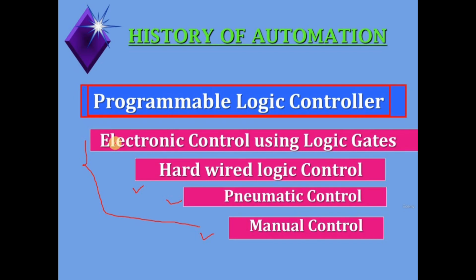Okay, it is like a rigid block. For example, if you are using the MicroLogix PLC, then definitely it will be a rigid block. If you are using the SLC 500, in that case you will get separate cards like a digital input card and a digital output card. Means it will be easier to find the input terminal and output terminal.